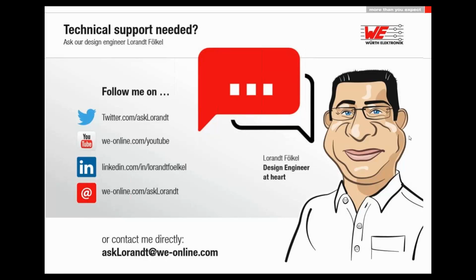Okay, next question. What is the definition of the different ferrite beads like high speed and wideband? Well, we made this definition on our own. We saw that we have over 4,000 different products for ferrite beads, and we decided that each ferrite which has, at the lower frequency, less than 10 megahertz, less than 10 ohm impedance, is good for high-speed signals.